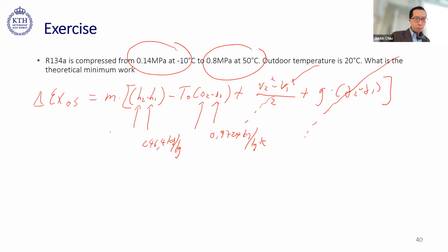So I just replace everything in. So H2 is 286.7 kilojoule per kilogram. And then S2, earlier we said, is 0.9803 kilojoule per kilogram Kelvin. And the unit here for specific entropy is the same as for your CP and CV. And the unit for your H is the same as, like, latent heat. I mean, it's the enthalpy, right? So then you calculate this.